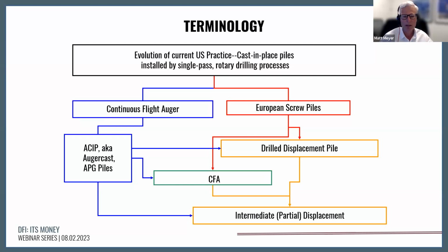That's in the category of the drilled pile, where we're not so focused on the in situ stress state and preserving the stress state in the ground, or maybe increasing the stress state in the ground, as we may see with the category of piles on the right in red and in yellow, which is our European screw piles, drilled displacement piles, intermediate or partial displacement piles. Those systems look at potentially enhancing the lateral stress, increasing side shear resistance through displacing action with specialized bits and tooling as you drill, and I'll say the word drill loosely, as you attempt to screw the pile into the ground.